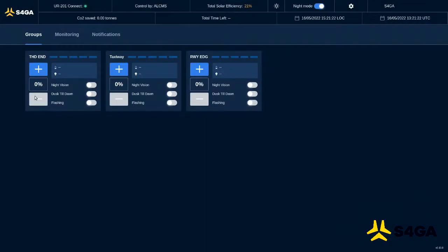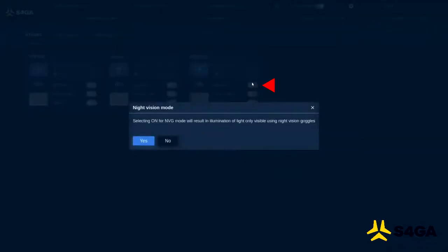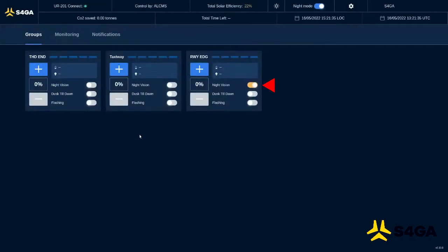How do we activate and deactivate those modes? First of all, if you would like to activate night vision, we simply click here, night vision. The system will ask for our approval to transfer between visible and infrared mode. We have to approve. And then the system will activate lights. Then we have to select intensity level. Again, we have five intensity levels in this mode. If you would like to deactivate the lights, we press this button right here and we change intensity level to 0.